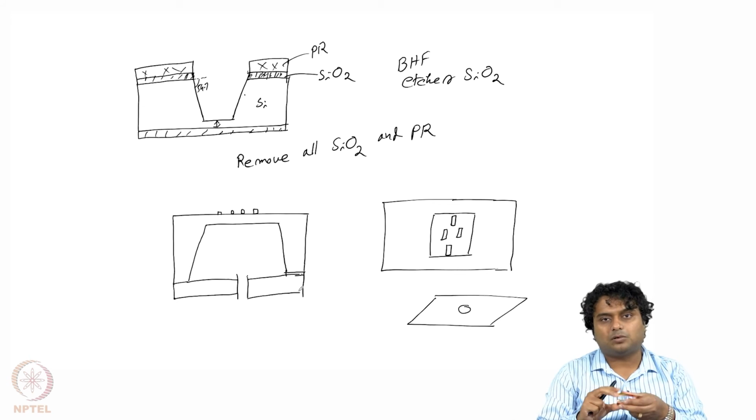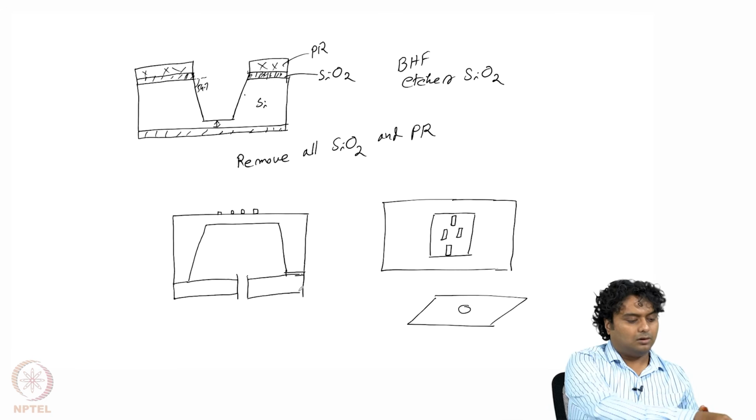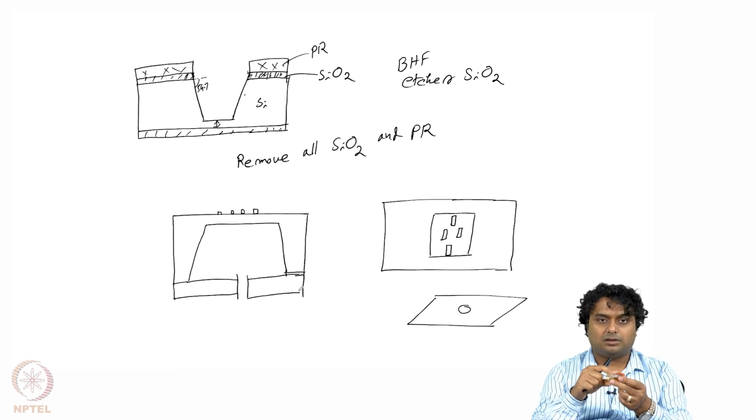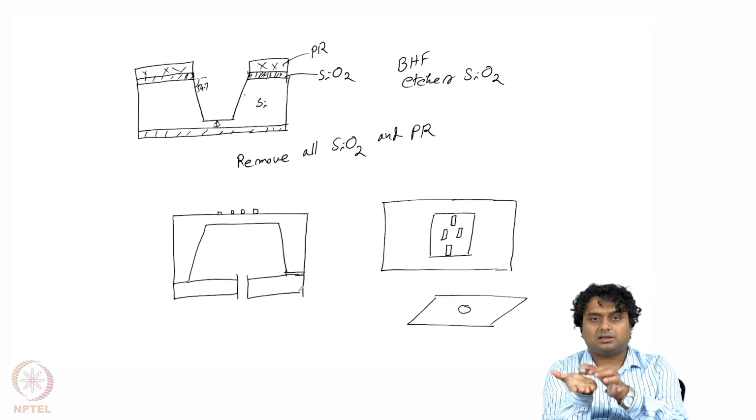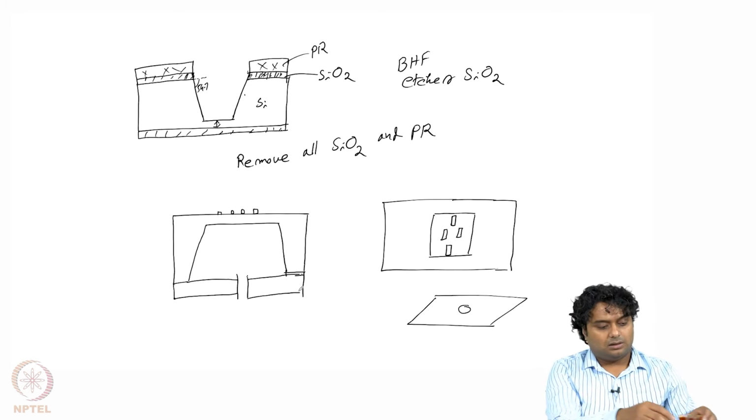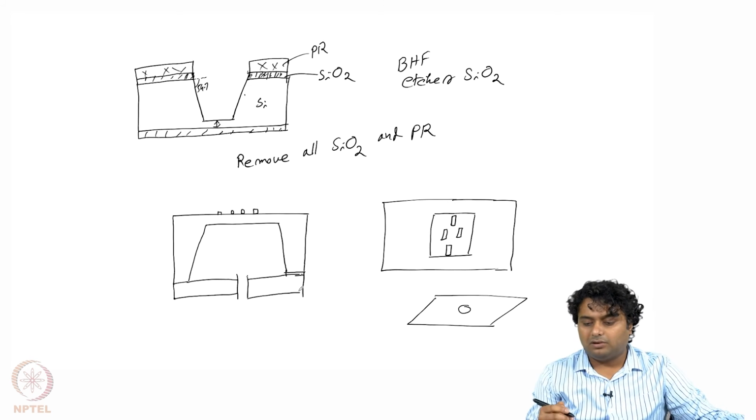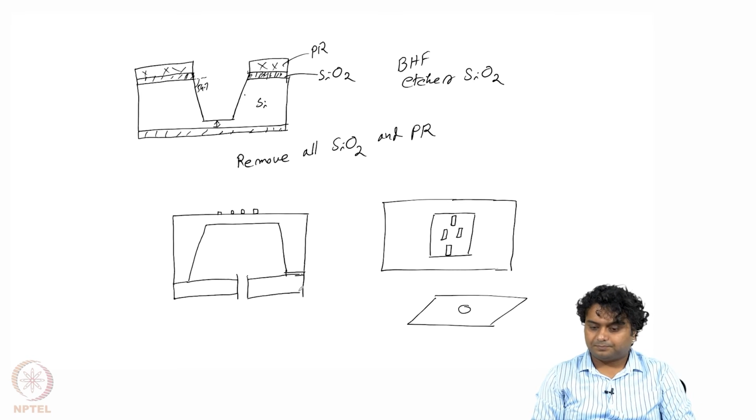So all the piezoresistors and etching have been done on this plate, and we have a cavity at the bottom, and then we just take another plate and stick it together or clamp it together by bonding, and then we have the full pressure sensor.